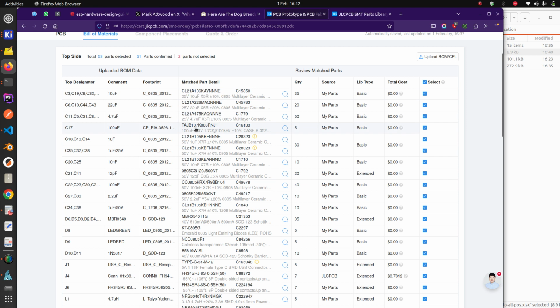and that the capacitors are capacitors and not, I don't know, resistors or whatever, because it can be that you just mismatch it or copy paste something in the Excel or whatever happens, and then you will place the wrong part in the same footprint, and that's really, guys, a bad thing to do. Okay, because JLCPCB is not going to check this for you. It's you who are responsible for uploading the correct files to the pick and place machine.